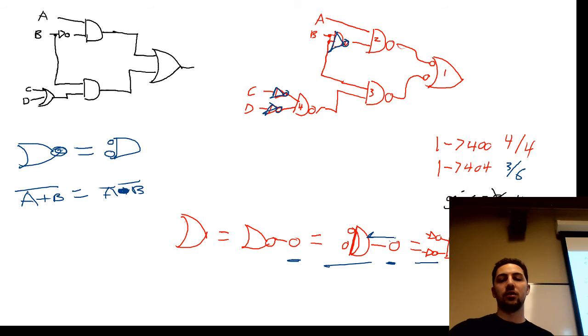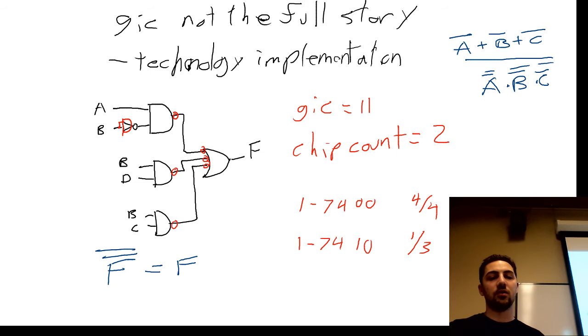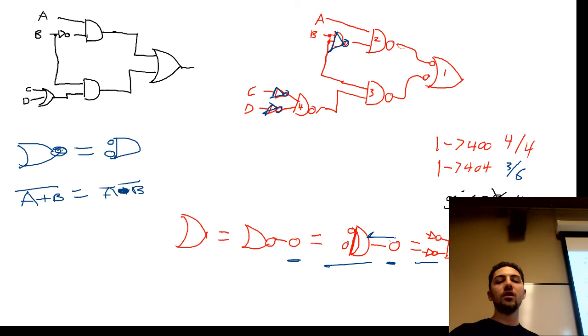this point here, where this is not the pen that writes on this tablet. Okay. Getting to this point and also doing this, putting down both is perfectly legitimate. You write, I'm going to try this, and I'm going to try this. And at the end, you say, oh, I'm going to do this one, or I'm going to do that one. From there, you take this diagram, plug it right into Multisim, and observe the output F. A, B, C, D go to your word generator. F goes to your logic analyzer.